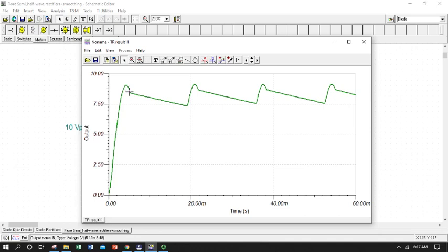It rolls down, and then the capacitor catches it and starts discharging, and this long descending line is the RC discharge curve of our capacitor and load resistor. So the capacitor is discharging through the load resistor, and it discharges down to about 7.5 volts before we have the next positive half cycle, and the diode is now conveying current. It's open and it's showing the voltage signal from the secondary. We come back up and the same thing happens again and again.